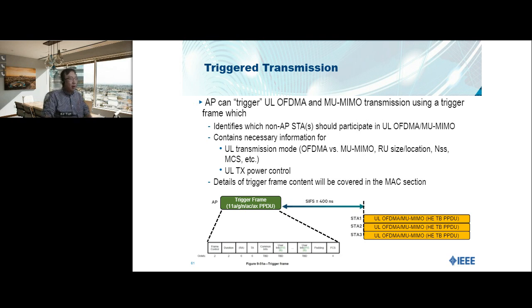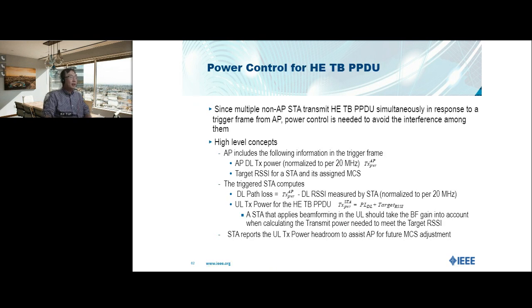It will also carry power control information, which I will talk about later. The details of the trigger frame content will be discussed in the next section, but I want everybody to realize from the PHY side that trigger transmission is scheduled transmission. So many things need to be defined, and there are many uniquenesses of trigger transmission from the PHY angle. The first uniqueness from the PHY angle is power control.